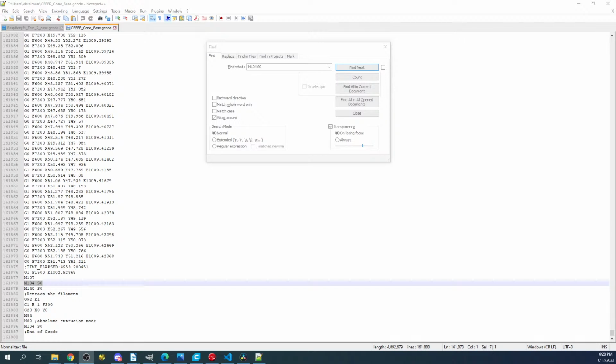So essentially, when this is running two extruders into here, what's occurring is only one comes out, but it thinks there's two heaters and two thermistors. So when it turns off this, it'll stop extruding. So the reason that I'm showing you this is so that you can decipher what's occurring on your printer and then plop it into a file and try it for yourself.